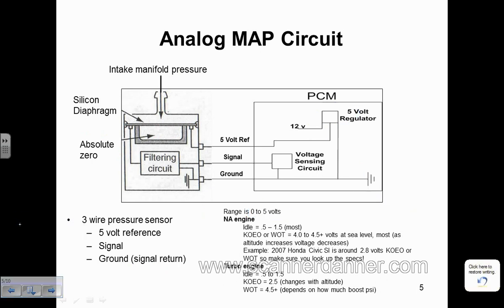What we're looking for is to be somewhere between 0 and 5. I'm just giving you an example that any sensor that uses a 5-volt reference, you don't want to see 0 or 5. We want to be somewhere in between. And these are good questions. I think the key to anything when we do diagnosis in this field is to have a checklist in your mind of quick checks that you can do on every car, that you're scanning different things.